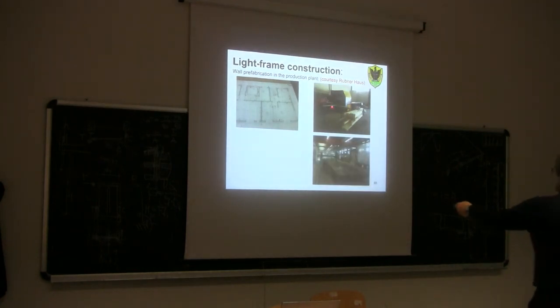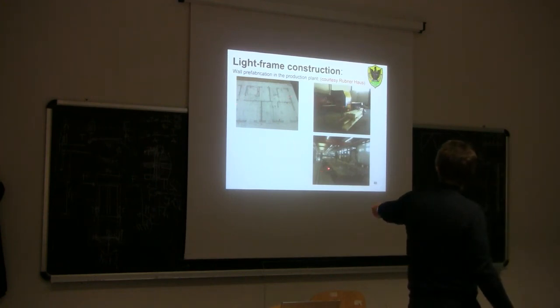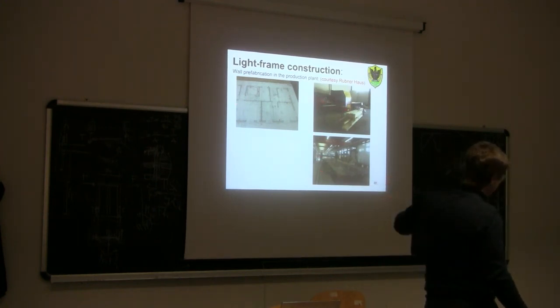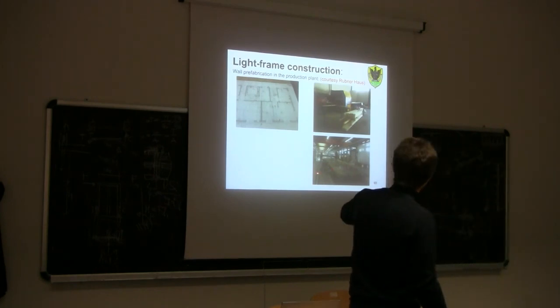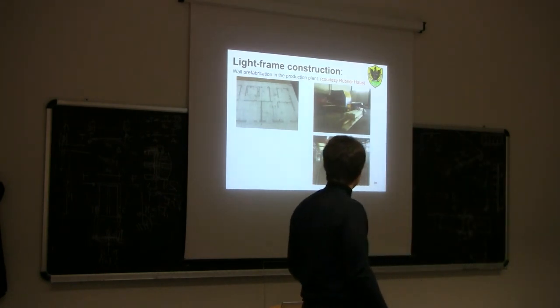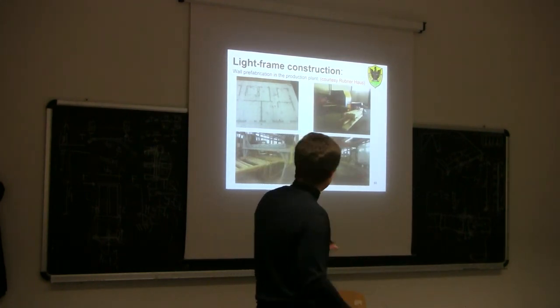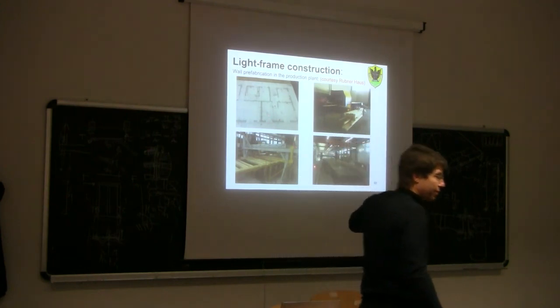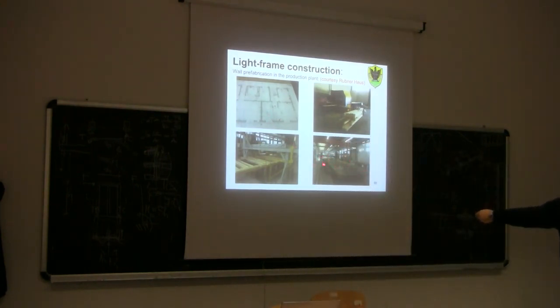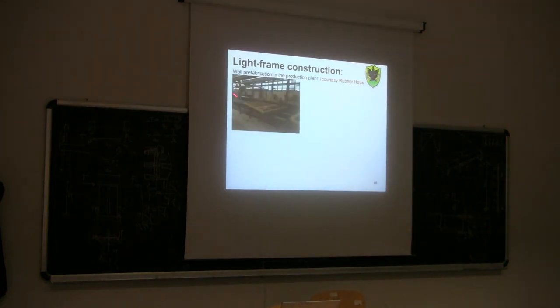You can see here in this machine, based on this project, they produce the frame. There is also a component, of course, not everything is fully prefabricated, there are also some men helping. In the end, you see all the pieces of timber are cut to size based on this blueprint. Then the bare frame is prefabricated using an automatic nailing machine. You can see here the bare frame produced by the workshop.